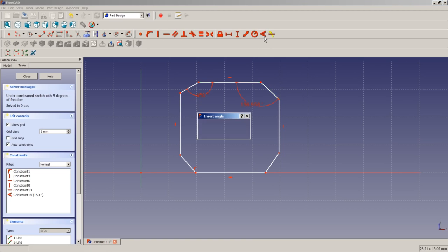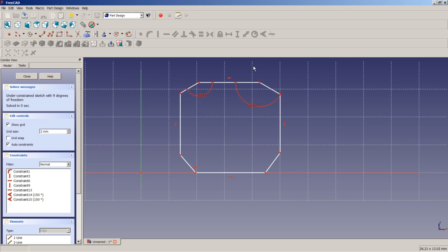We also need here an angle of 150 degrees because DIN ISO says that this angle here should be in total 60 degrees, and this slope here can vary between, as far as I know, if I recall correctly, 15 and 30 degrees. So let's choose 30 degrees so that this angle here is 150 degrees because a horizontal line would be 180 degrees.